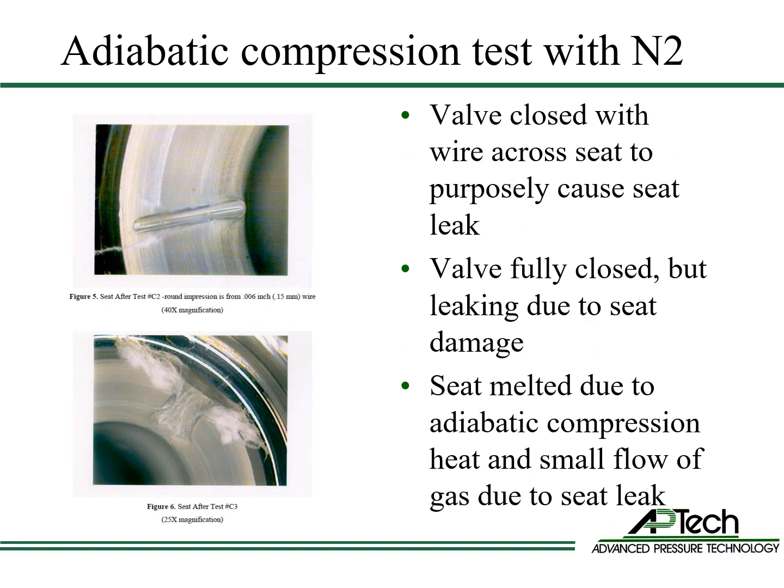In another lab test, a valve is closed with a small wire across the seat to purposefully cause an across-the-seat leak. The seat melted due to adiabatic compression heat and the small flow of gas due to the seat leak.